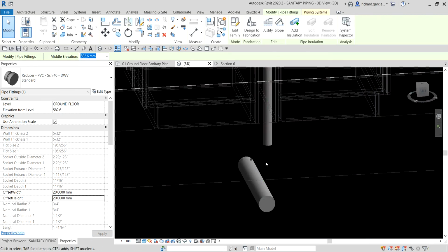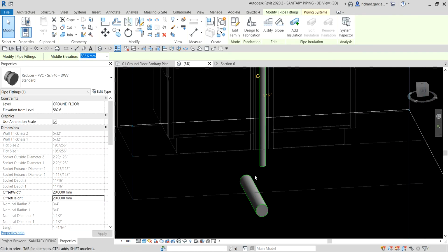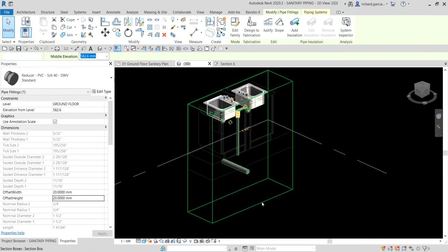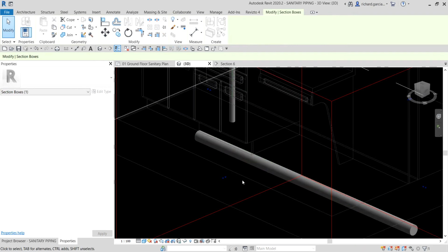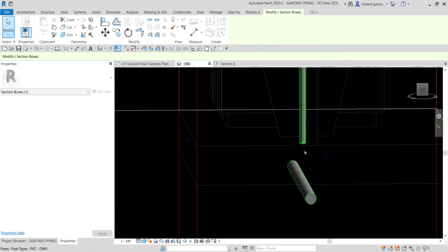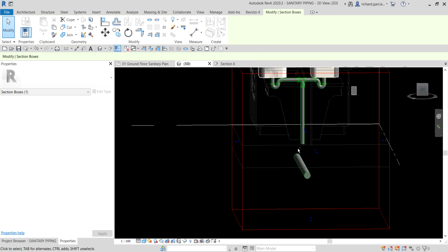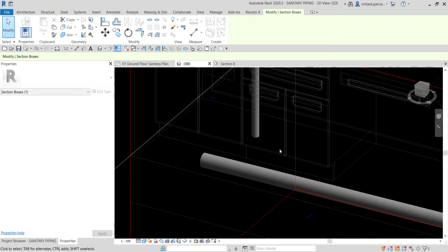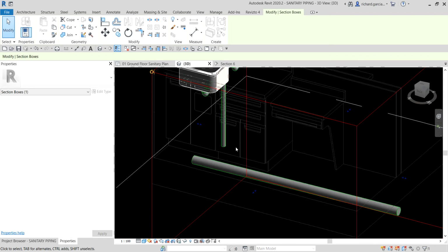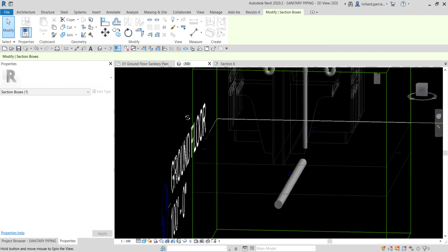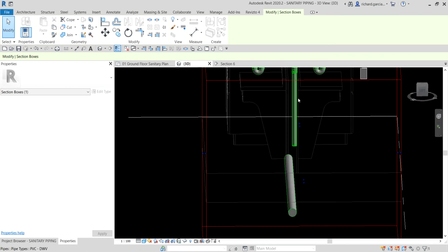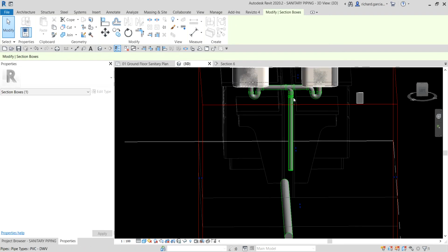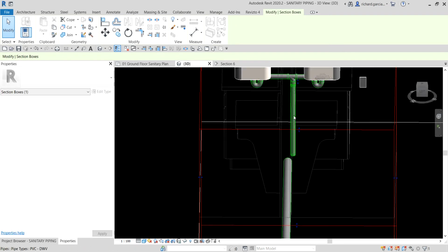But the problem is it's not aligned here anymore. Now, another tip or technique of modeling. As you can see, they are not aligned here anymore, right? So another tip and trick in modeling a pipe: you can use move, right? You can go to the top view and then just move this pipe until it aligns or hits that center line when you move.